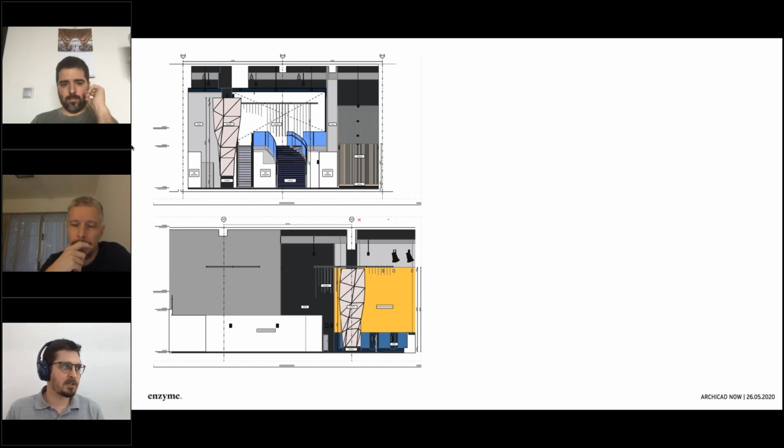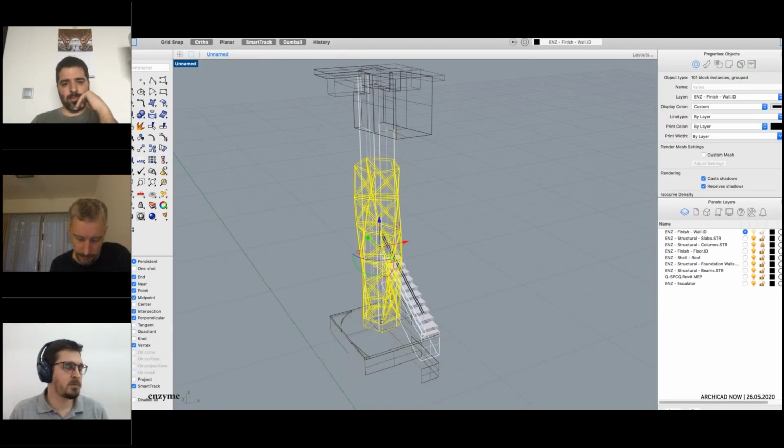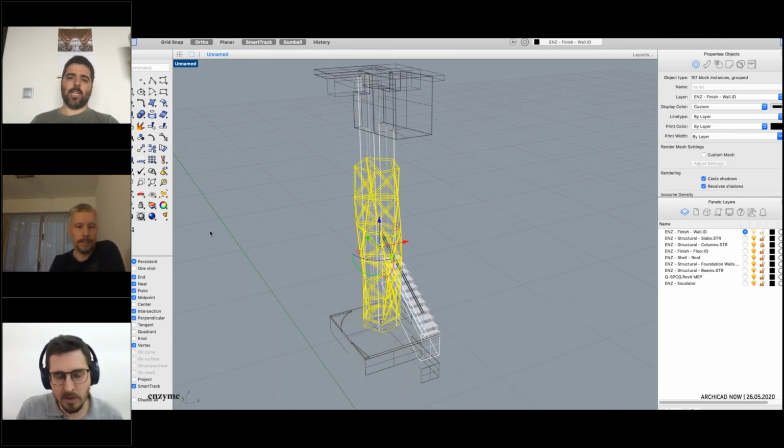Okay, so yeah, with Rhino Grasshopper and these large files, the live link can definitely slow ARCHICAD. So what we did, as I explained, was first save a portion of the ARCHICAD model, a very small one, using a marquee. I can show you here. If you can see the screen, it's just a rectangular marquee, and using that we created the algorithm in Rhino Grasshopper. Don't send the whole file back and forth, right? Just work on small pieces.